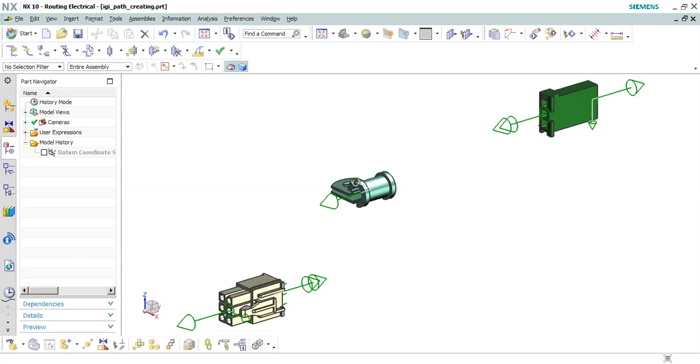The first thing is the main routing. The main routing elements are paths, control points along the paths, termination connectors which have ports for alignment, and stock that represents wiring. Standard parts for electrical routing would be connectors, butt clamps, tie wraps, and other similar parts.